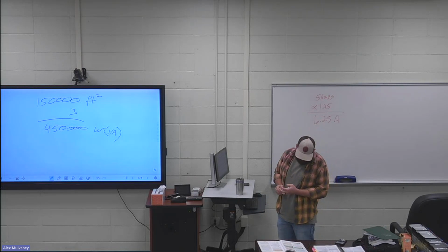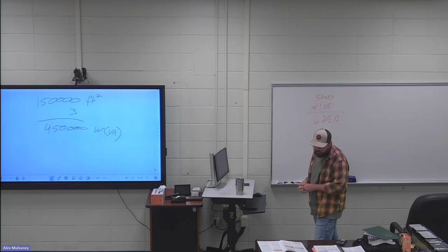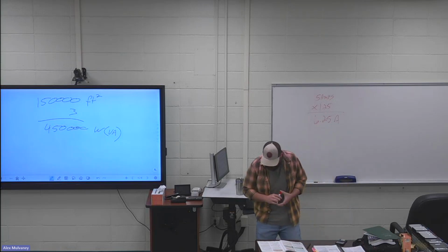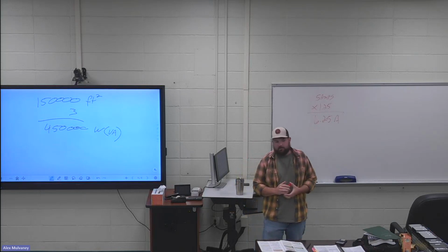The last sentence is what you want to key in on. If you have fastened in place utilization equipment, it can't be more than 50% of your entire load. So on page 3, they're going through all the problems to figure out what the circuit load is.